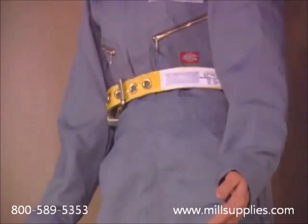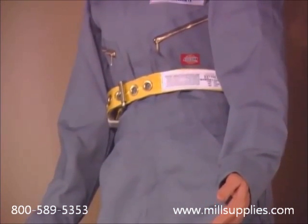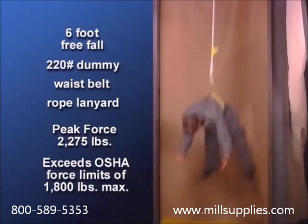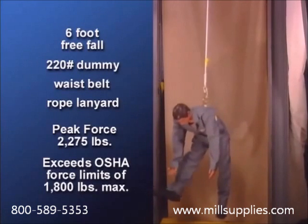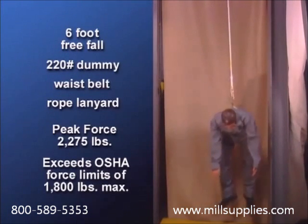Body belts are not recommended for fall arrest. In addition, most regulations governing fall protection prohibit the use of belts. In this drop test, a dummy is dropped into a body belt. Note how the fall forces were concentrated on the abdomen. Such forces concentrated on the abdomen could cause serious internal injuries.